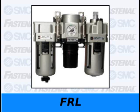Even though there's already a mainline filter, this point-of-use filter on the left catches any last debris from the piping, and any moisture that is condensed along the way accumulates in the bowl. These also have an optional auto drain, which is a good idea, because you'll find that people tend to forget to drain them, and problems follow.